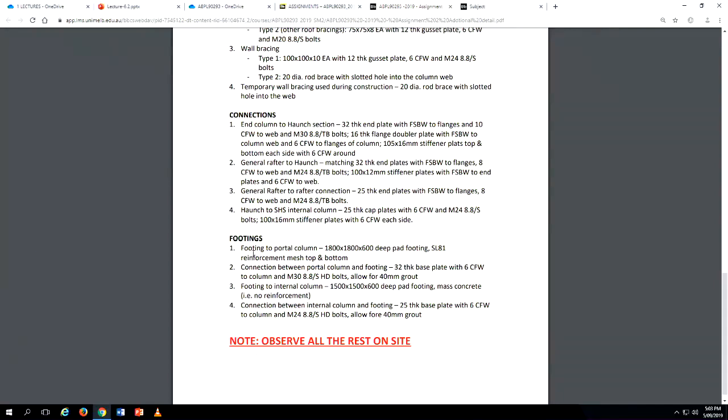So if you look at the footings, there's something I need to tell you as well. Because some of the elements, they have used different elements. Like the footings, they have different pads, but I've just given you one size. So just take all as the same size. They've got footings up to 2.7 square as well. They've got 1.5, 1.8, 2.1, 2.7. But the most common one was 1.8, so I took 1.8 square. So when you go to site, if you see that, just ignore. Just assume. There are many other elements that are different, but I've just taken standard ones.